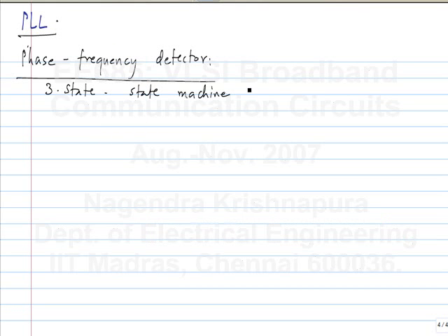What is the gain of this phase detector? So, let us say the phase frequency detector gives you either 0 or 1 volt at its output, right. It has up and down outputs and it gives you either 0 or 1 volt. Okay. What is the gain of the phase detector? 1 by 2 pi. Yeah. So, if the output is 0 or let us say Vp volts, the gain of the phase detector will be Vp by 2 pi volts per radian. Okay.